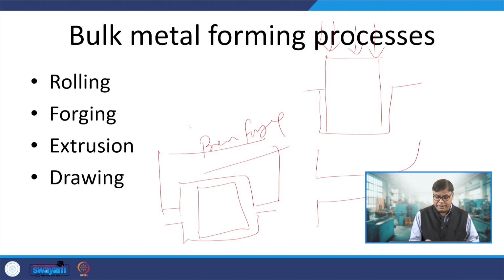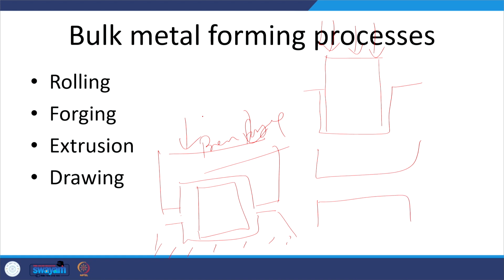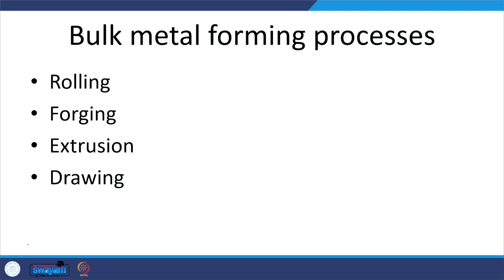The upper die will be lowered and the lower die will be kept on the anvil, and when the upper die is moved in a controlled way with the help of a suitable press by increasing the magnitude of the pressure continuously, the metal in between the dies is forced to flow plastically, okay. So, that in turn helps in achieving the desired size and shape.